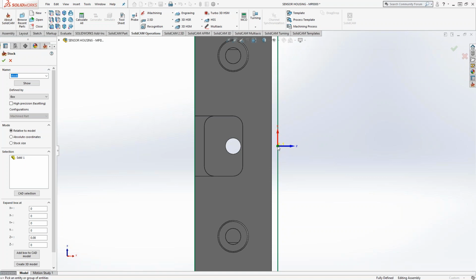From my experience, it's just a preference, I think. Kevin, what do you think? The reason why I would definitely prefer top center than anything else is because the majority of the machines out there come with the probe. So when you go to probe up your part, it's much easier to do a probe web and much more accurate than it is to probe off of a corner. So this really works well with your saw cuts. It will always go off of the center of your part. So if you have a saw cut on both your X positive and X negative direction, it's going to center that as well as your Y direction.